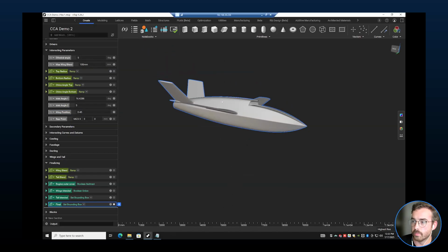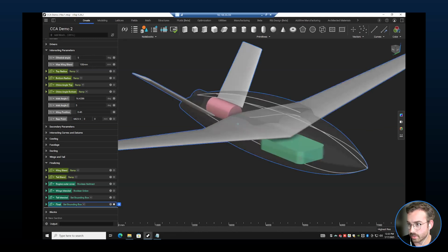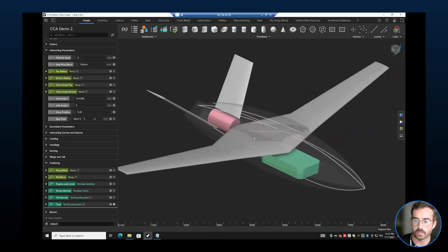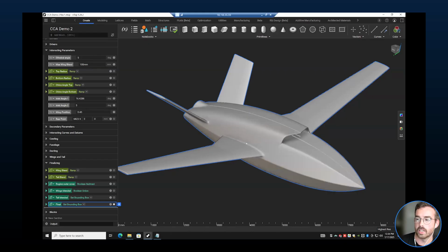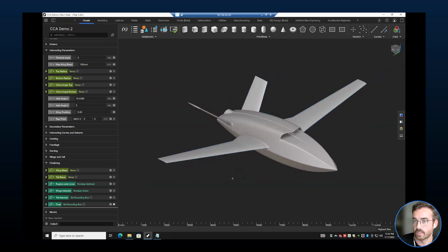Okay, so that's kind of overview of the model. Like I said, things to keep in mind are curves, implicits, and then building blocks. So we have this final geometry, but I also have the building blocks in here of the wings and the tails in there. The unique thing about working in this kind of procedural implicit way is, unlike with BREPs in CAD, where you're kind of like constructing one big set of surfaces, trimming things, discarding things, all of that, you have everything accessible to you along the way. So even though I'm kind of consuming these wings later to create the final body, I still have the wings as individual bodies elsewhere. So that's what you're seeing here.